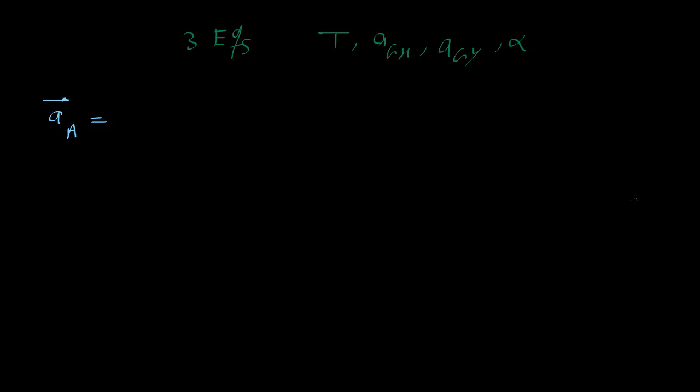Writing down the Euler and Newton's equations, and then using the geometrical constraint, the constraint from kinematics, to come up with more equations so that we can have the same number of equations as the same number of unknowns. This is a very important analysis in solving problems, and basically it just tells you what direction you have to go. If we had the same number of equations as unknowns, then we just go ahead and solve them.